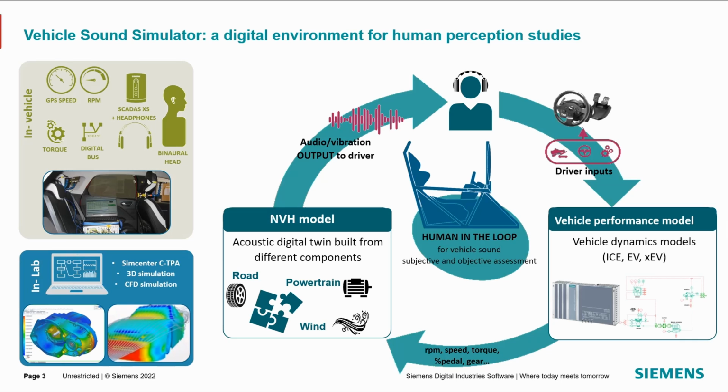Instead, in terms of the dynamic vibration excitation, you have first when the launcher is released from the tower. And second, you have the shocks when you have the stage separations. So you know that you have these kind of exploding bolts that connect all the stages. And when these stages are released, shock type of excitation will go into the connection between the launcher and the satellite itself or the base. So that is this type of shock.